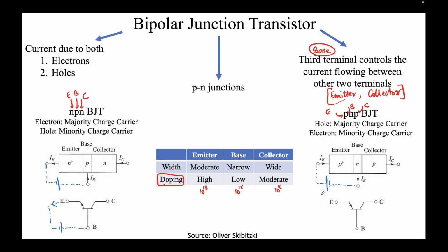You will not be able to identify them, right? There are some markings on the device itself, but when you draw on paper, how will you distinguish between an NPN and a PNP BJT? This is how we distinguish, by just this arrow. This arrow primarily denotes the direction of current when we apply a forward bias. That's all that the direction of that arrow means, okay? Not the flow of electrons or flow of holes, but the flow of current in both NPN BJT and PNP BJT.